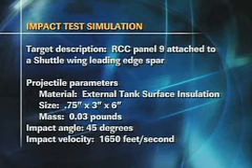With RCC, we had very few RCC resources. We didn't have much material to work with. We had to be smarter about exactly how we used the RCC in test. And so most of our thresholds are actually based on analysis and verified by limited testing. Some small-scale coupon testing and even more limited full-scale panel testing.